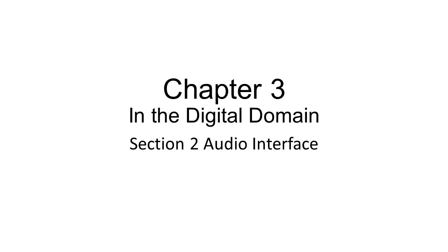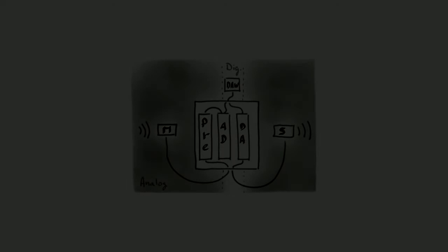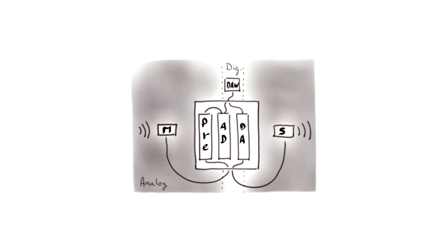In its simplest form, the audio interface is an AD converter and a DA converter. In higher-end models, it can also contain components such as mic preamps, EQ filters, compressors, MIDI input and output connectors, etc. If we look at Figure 14, we have a single microphone connected to the audio interface, usually via an XLR connection. Within that audio interface, a microphone preamplifier adds gain to the signal so that it can be properly processed by the AD converter.